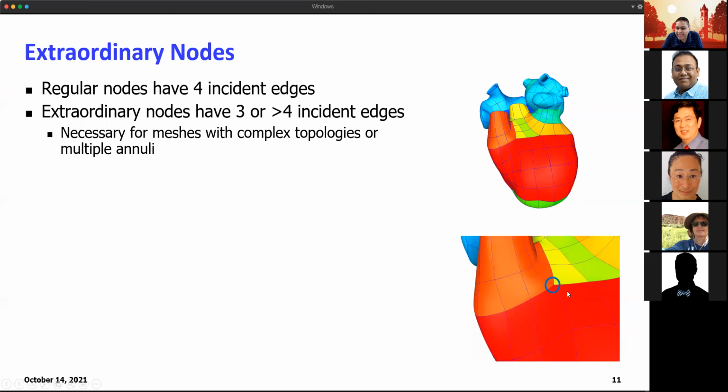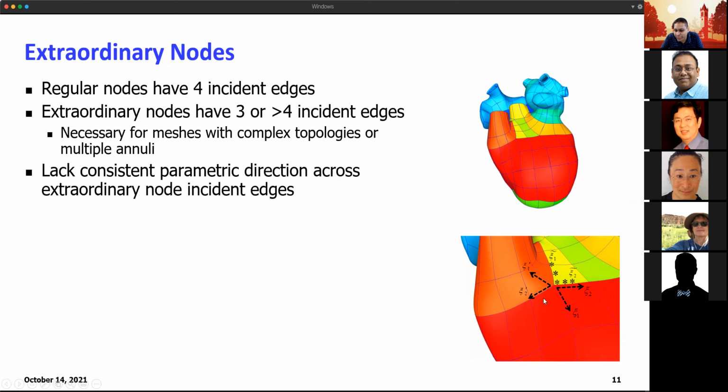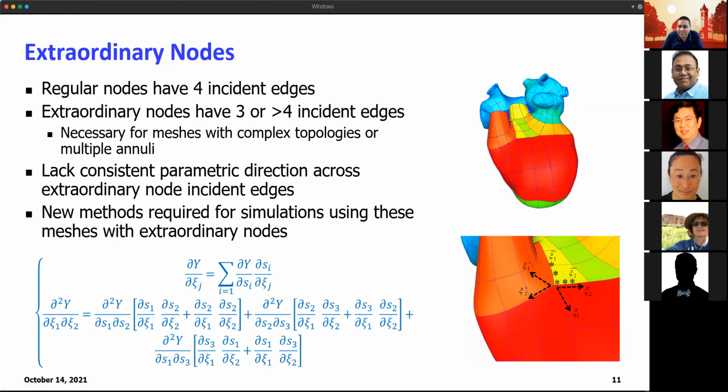If you're doing it linear, there's no issue because essentially each of these will be line elements. On the other hand, since we are doing higher order elements, what we need to do is maintain the derivative across these lines, which are shown here. And essentially, we have developed a mathematical approach where we can use a single set of coordinate system and then map it to that coordinate system to get these smooth elements to work out. Obviously, I'm not going into details, but if you have any questions, feel free to ask me later.